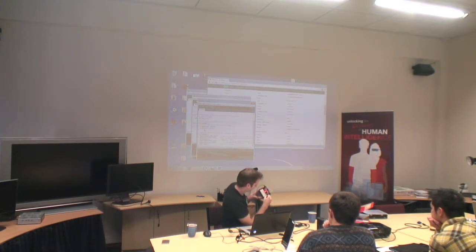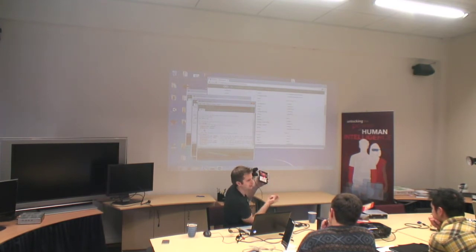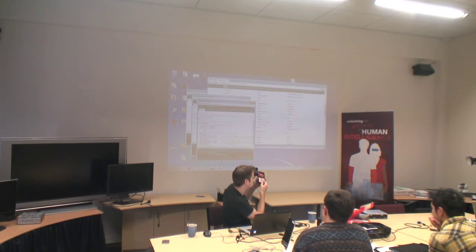So all of these ones are connected and all of these ones are connected, but these ones are not connected to these ones. If you look at how I've connected it, this wire here connects to one leg of the LED and then that one goes into the next slot along this way, because if we put them on the same slot, it'll basically be a short circuit. So you want to connect all your things down the breadboard like that.